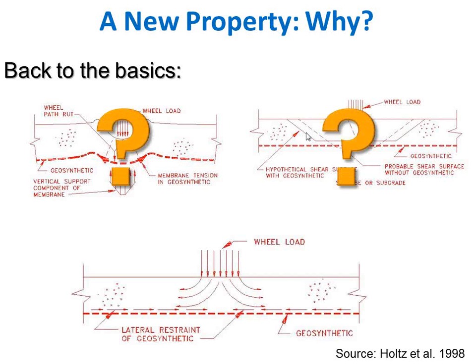If the base distends laterally, essentially we lose confinement. If we lose confinement, we lose stiffness. If we lose stiffness, we have a lower performance in the pavement.